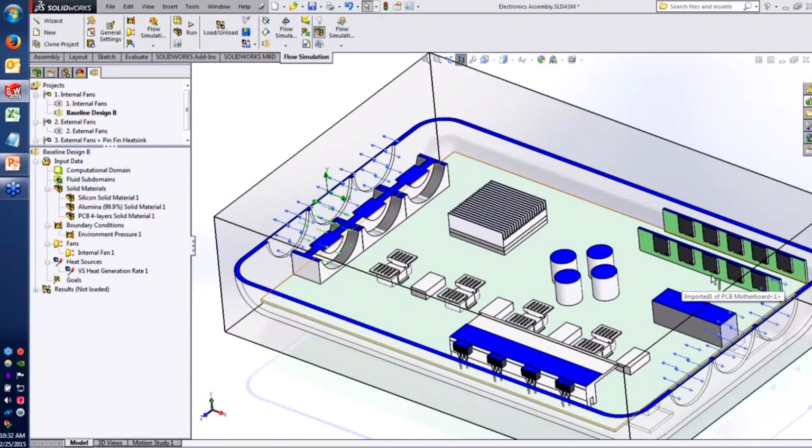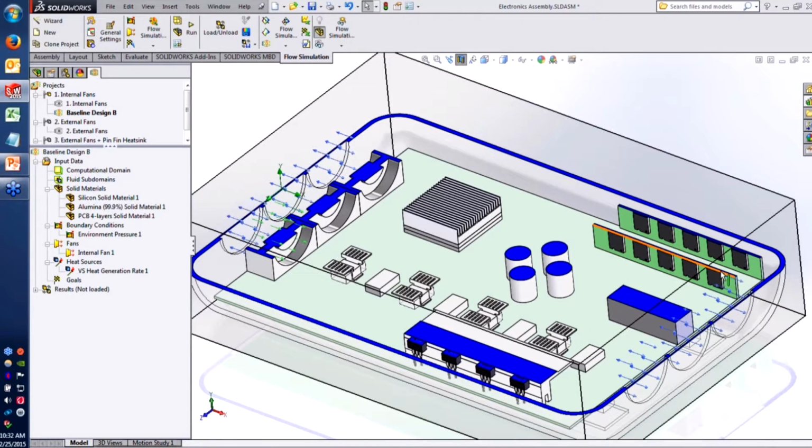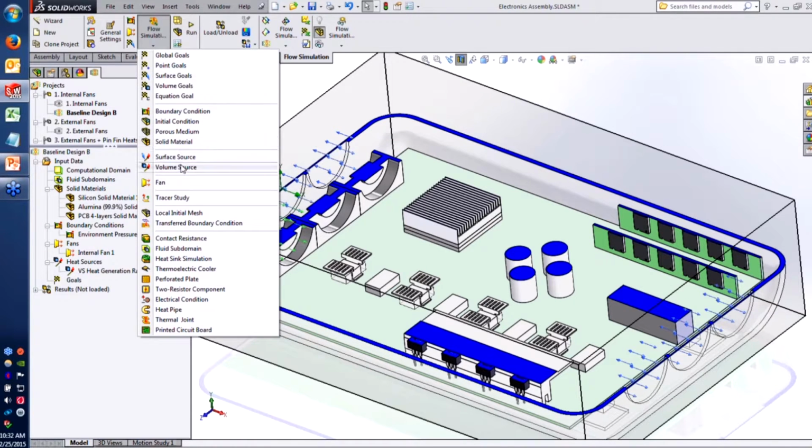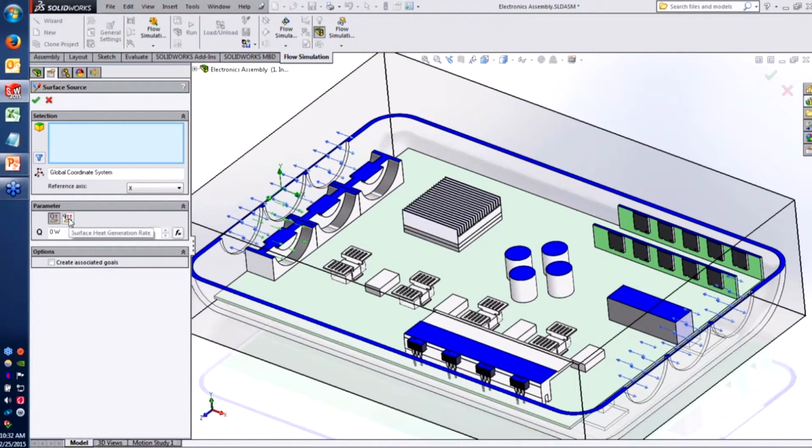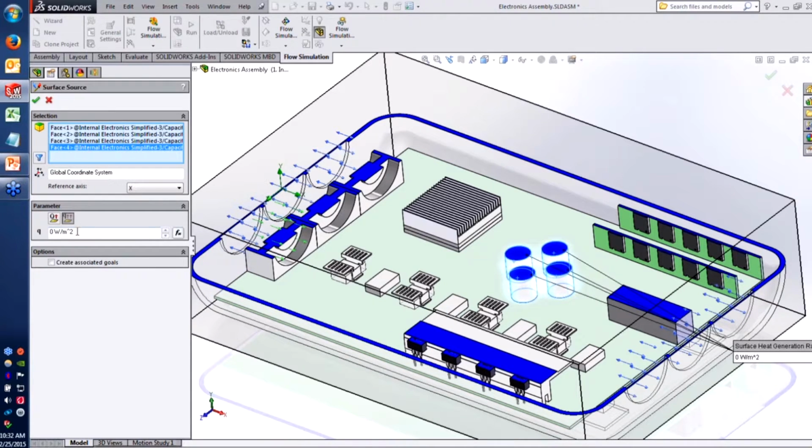And usually most chips will have a thermal design power that you could look up and choose that number from. And maybe we would set the other components, like these chips on the RAM sticks, to have their own wattages, or we could even do things like define a known heat generation rate, which is basically just wattage per area. So it's similar but a different unit.